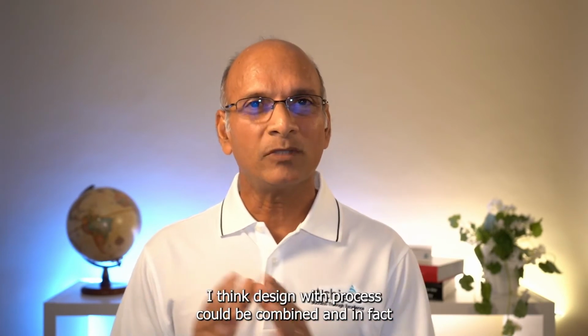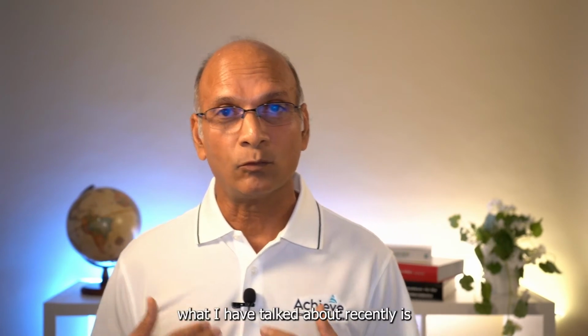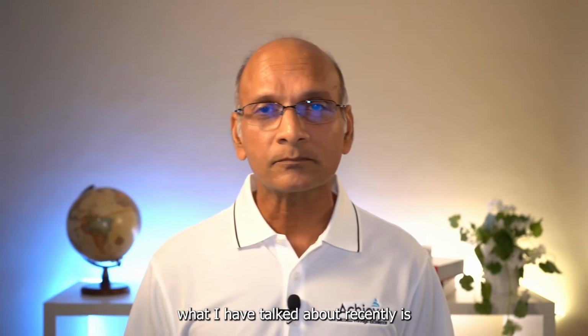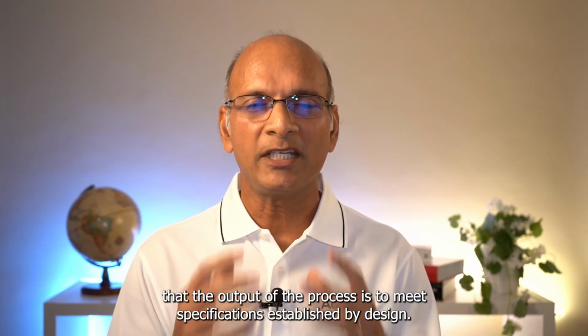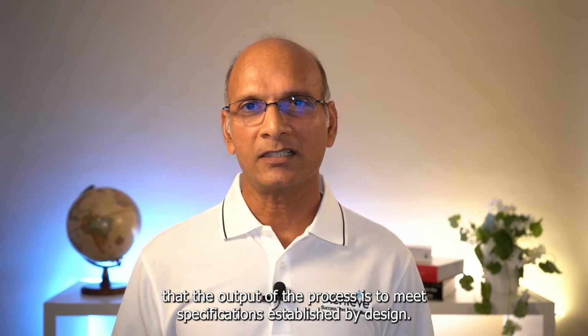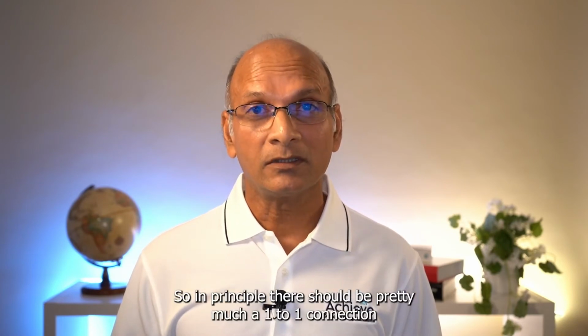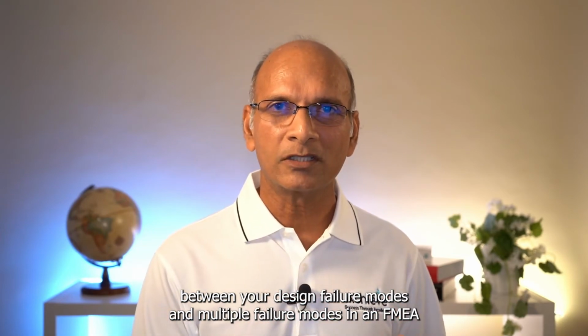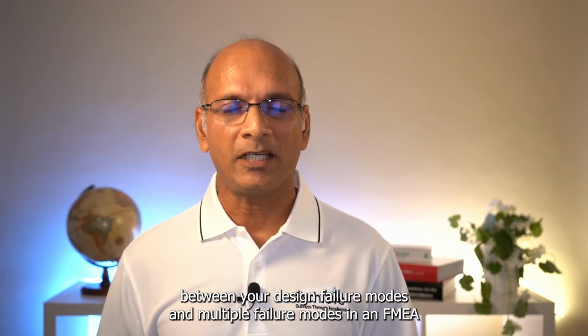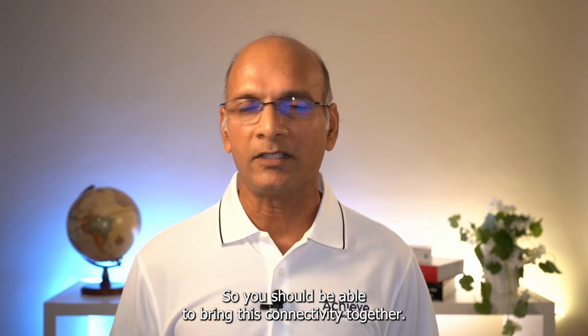I think design with process could be combined. And in fact, what I have thought about recently is thinking of process in the service of design, that the output of the process is to meet specifications established by design. So in principle, there should be pretty much a one-to-one connection between your design failure modes and your process failure modes in an FMEA. So you should be able to bring this connectivity together.